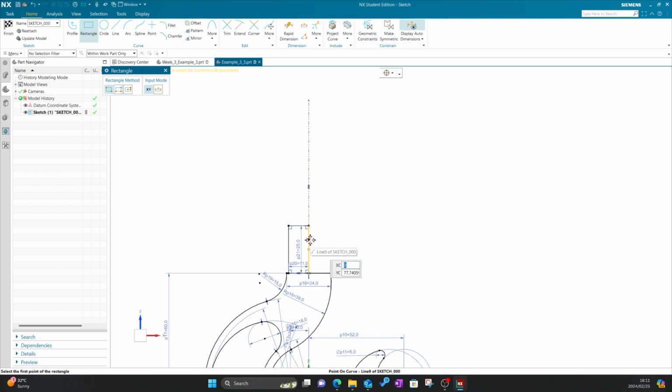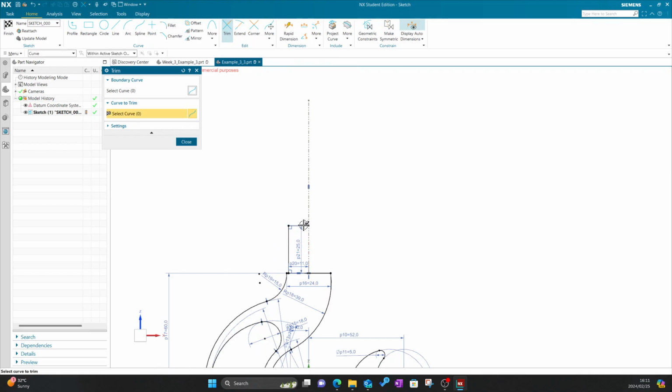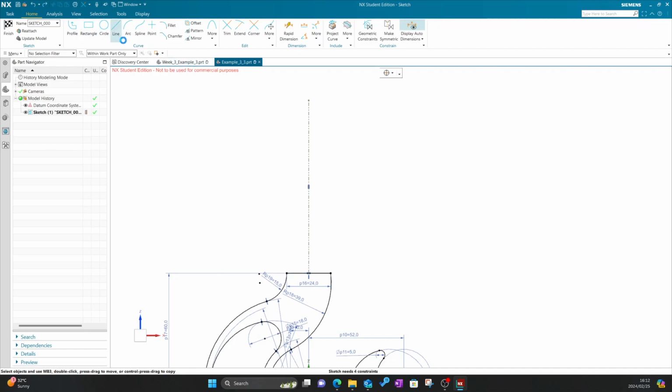The only thing now is there's a line there that will mirror once I mirror it, so I'm going to trim that line away. So now you only have that. So rather than using this box feature, the better way when you want to create the mirror is I'm just going to use line.